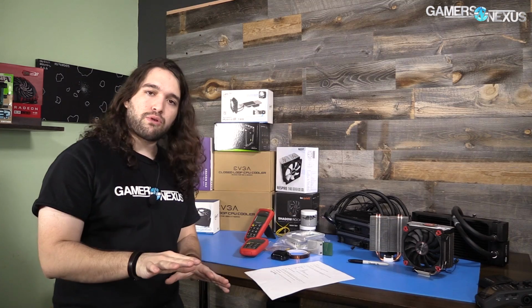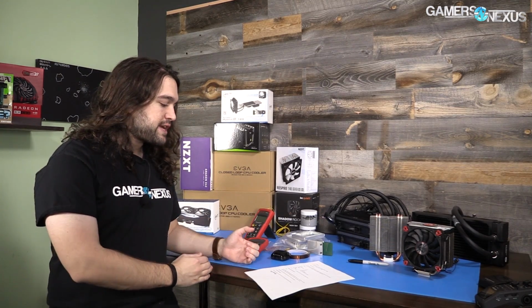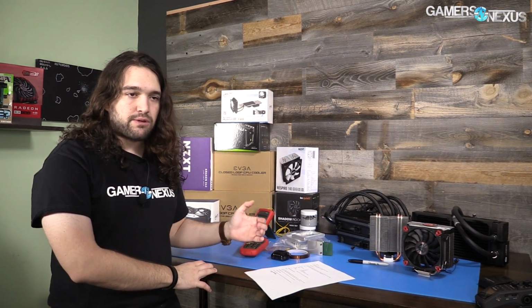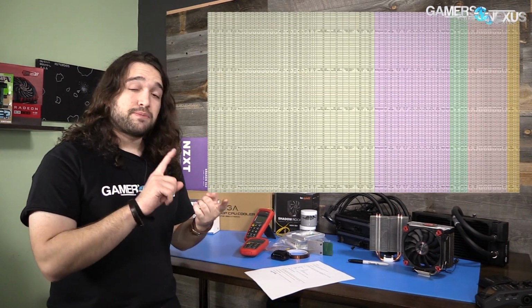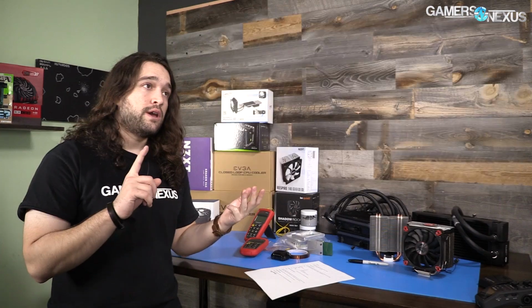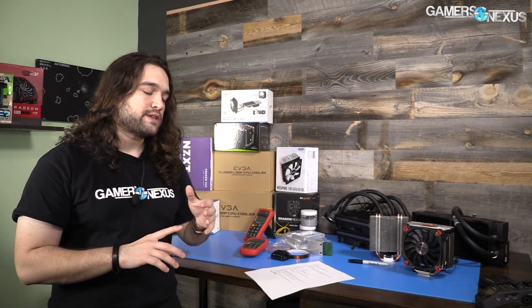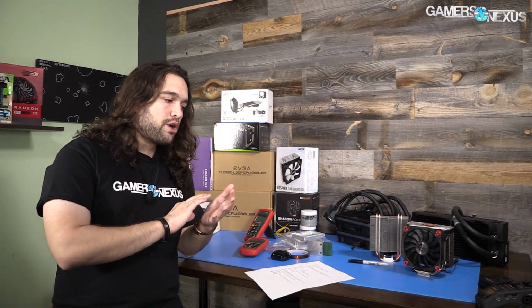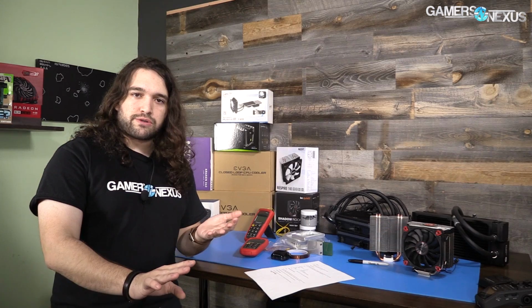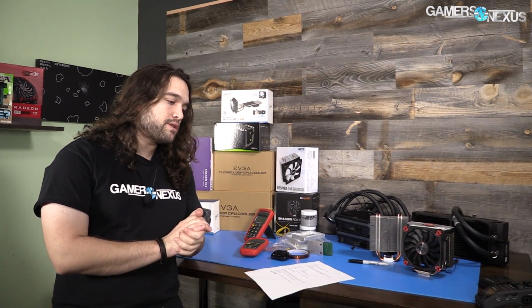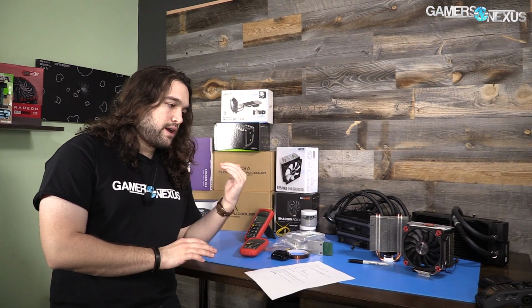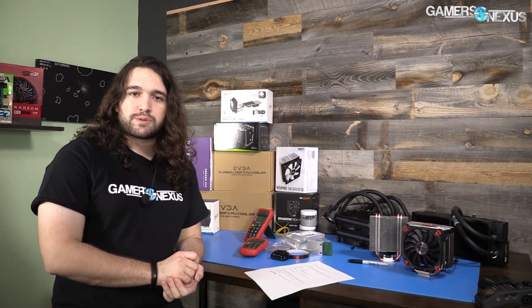Software is also really important though. Once you've got a base understanding of it, turn on logging, run it for the entire test, and generate logs for everything because it doesn't hurt to have more data. So we generate logs for CPU frequency, CPU utilization, I'm talking about this cooling testing obviously, vCore, all the voltages, all the power draw measurements, sometimes it's accurate, sometimes not, depending on the software and the CPU, and temperatures, and then dump everything into a spreadsheet.